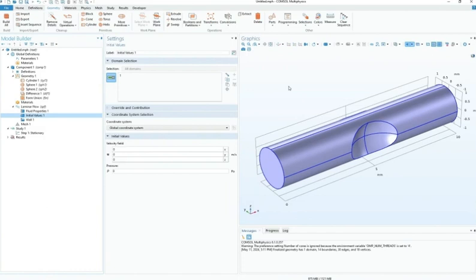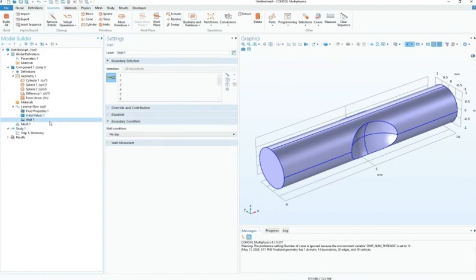So our first step would be that we would go over here to the wall selection, and then we will move to wall movement. After being in wall movement, instead of having an automatic frame translational velocity, we will make it such that the translational velocity is 0. So it's as if it's a fixed wall.